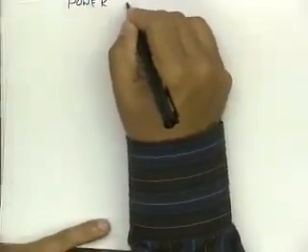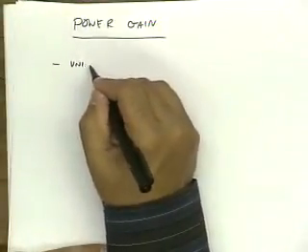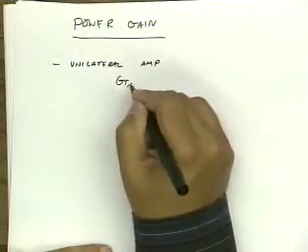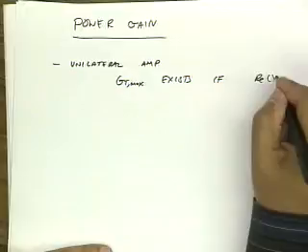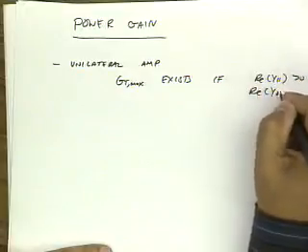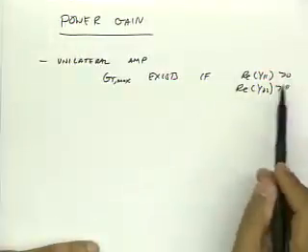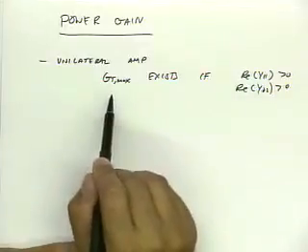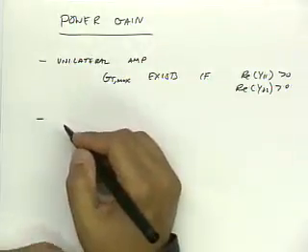equation, this question of power gain in general. So what we found is that for a unilateral case, GT max exists if simply real part of y11 is bigger than 0 and real part of y22 is greater than 0. And if it's a physical transistor model, usually this is true. So you almost don't need to check this condition, but usually it's already satisfied. So for a unilateral amplifier, we can always find the maximum gain. On the other hand, if it's a bilateral amplifier,